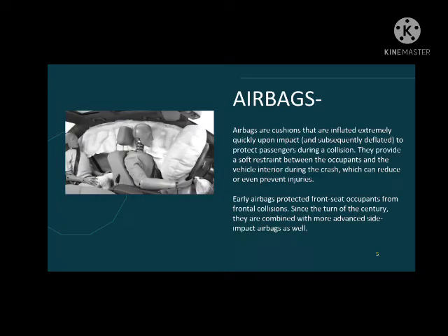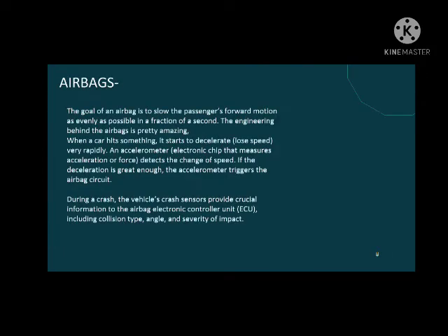Airbags. Once a crash has been detected, a flexible bag is rapidly inflated with a gas that is released from a container by an electrically ignited chemical component. Ideally, the airbag inflates in sufficient time, typically less than 50 milliseconds, to act as a cushion for the driver or a passenger as he or she is thrown forward or sideways during the crash.